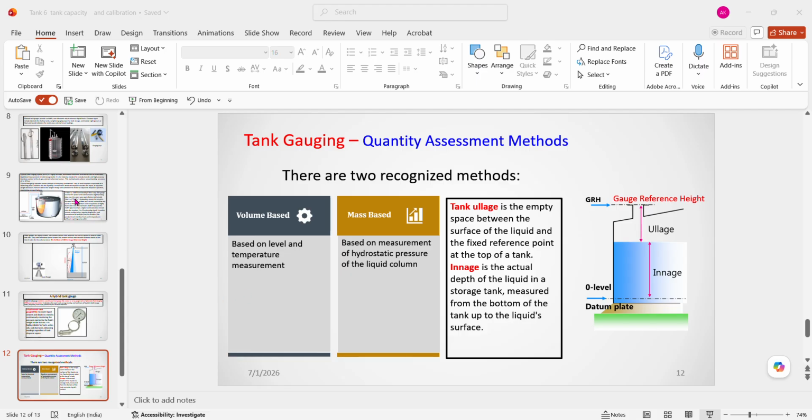That also you come to know by this pressure, density, water bottom, and temperature. Temperature also you have to measure for level compensation. That is all in the tank gauging system. That's why ATG is very important for any tank.